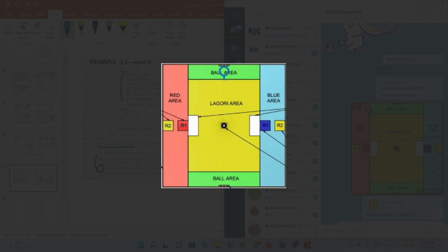If you have the orientation, that's right. You apply it to the set of points of the robot frame, using the rotation matrix to transform it into the global frame. Then you add those coordinates to the origin x and y computed from Q, and then you have the robot shifted to another place accordingly, right?